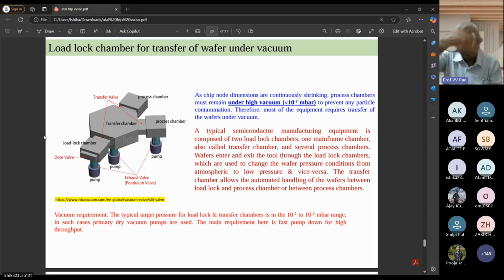This can be calculated from the surface areas and, say, Monte Carlo techniques. How much is the molecular density at this pressure, that pressure? And if that pump is not good, the central pump should be much bigger, larger volume, more setup. But even if it is a larger volume, if you don't mind waiting for 1 or 2 days, then it can be a single pump because it is leak tight. But even if it is a single tight pump, and even if you can afford to wait, if there is a leak, you will never get the proper vacuum where you can even start. So it is give and take; a lot of things have to be done.